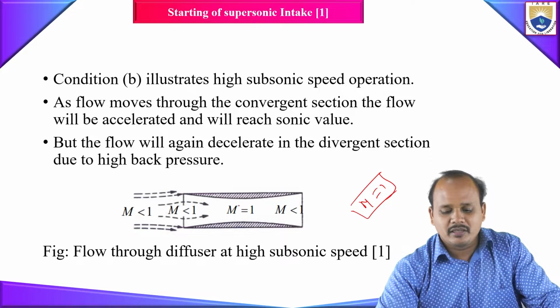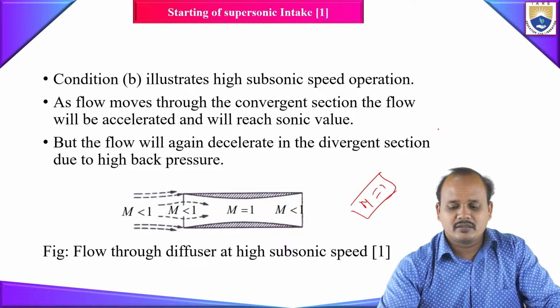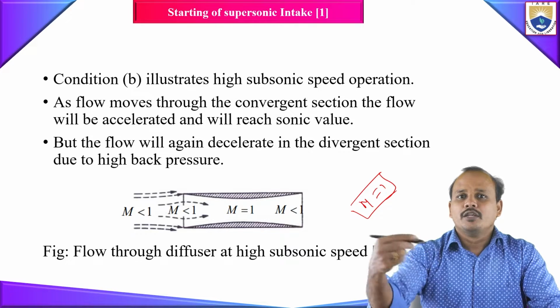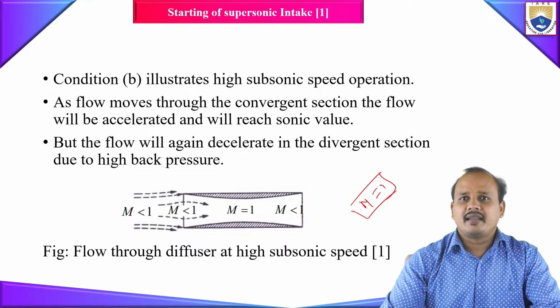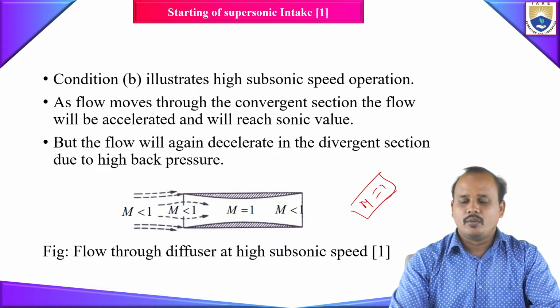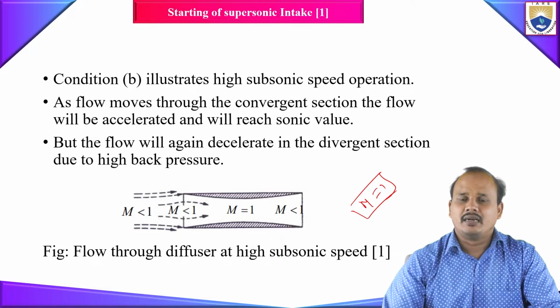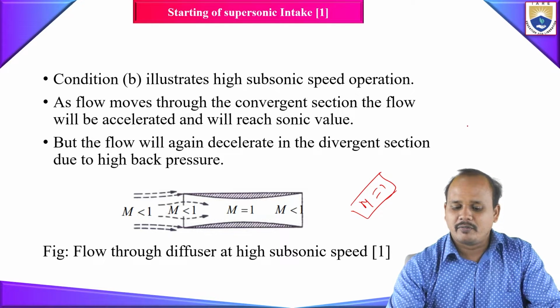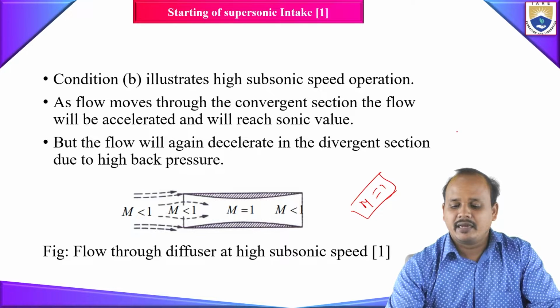Conventionally in your nozzle, as you know, in a choking condition, once your Mach number reaches a sonic value at the throat location, you will have acceleration after that, right? That is, if the supersonic flow enters a divergent section, your flow will be accelerated. But here I kept my exit Mach number at my throat, your intake, less than 1.